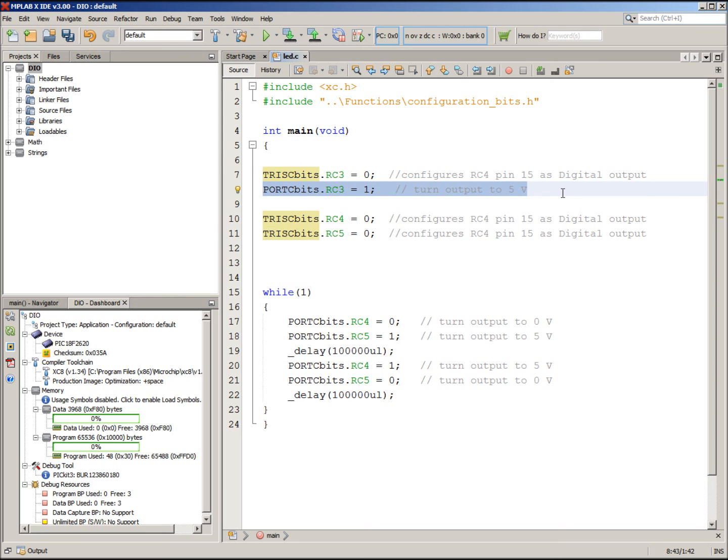You need to know a little about how LEDs work to make them light and how you make connections with them. And if you want to do anything cool, you usually need some sort of delay function in here to make lights blink. And as mentioned in the code, if you cut this down to something like 100 instead of 100,000, that flashing will be so fast you won't see red, green. You'll see a continuous mixture of them that will look kind of yellowish or orange, depending on how long a time you've chosen.